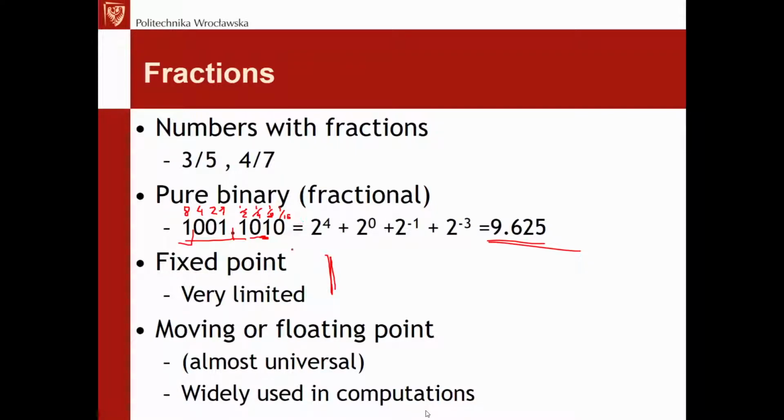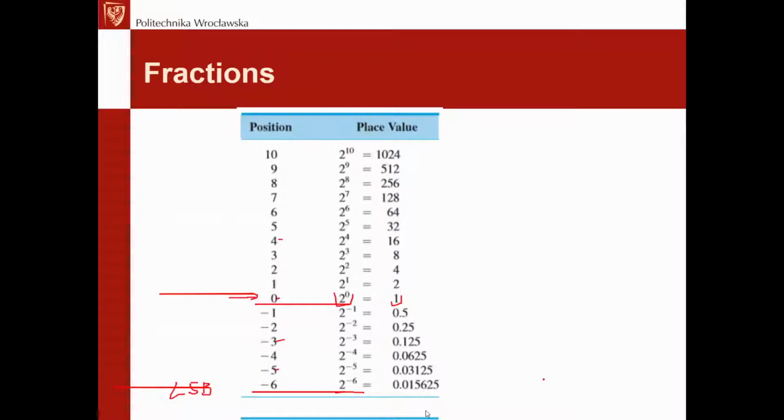But with an 8-bit number, the integer part can be only 4 bits here with the decimal point in the middle. So minus 8 to plus 7, and the fractional 1/16, which isn't too high precision.